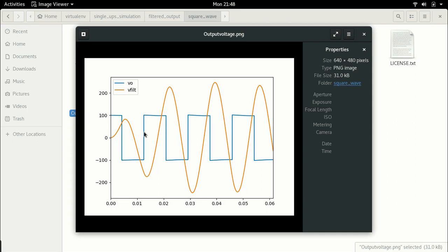An inductor is an energy storage element. So it stores charge and it discharges again. It stores it, releases it. So when this energy gets released, it gets released into the output capacitor, which is why the voltage of the output capacitor is greater than the voltage of the inverter output. This is nothing much. If you go back to your basic power system concept, you would have learned this. A lightly loaded power transmission line can have a voltage at the receiving end which is higher than that at the sending end. Why? Because all the charging capacitors throughout the line are now adding their voltage, and the result is the voltage at the receiving end is greater than that at the sending end.